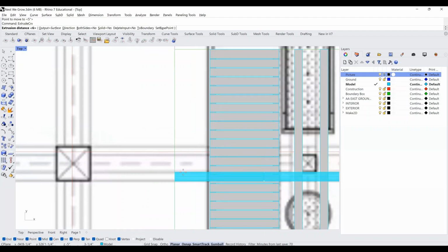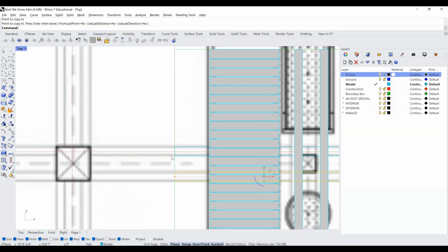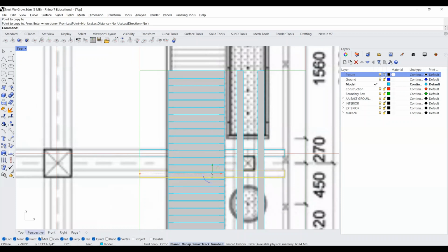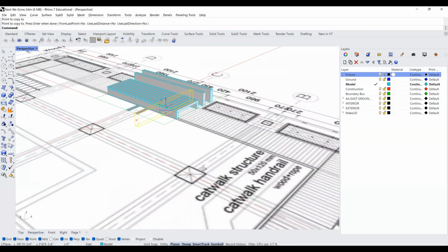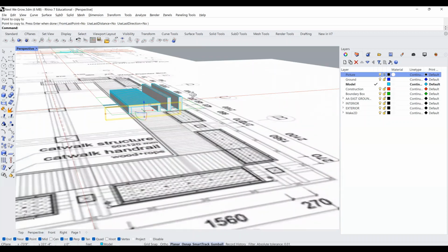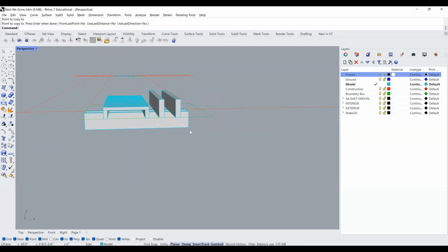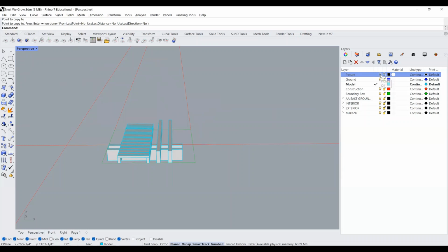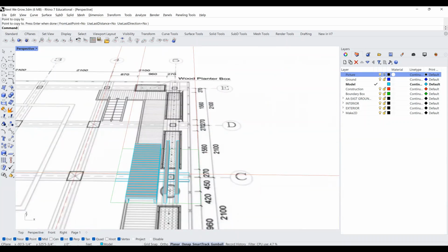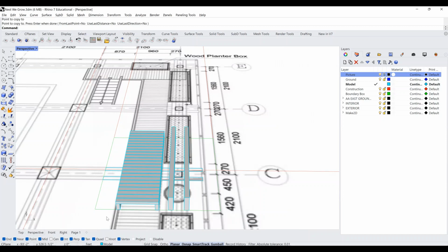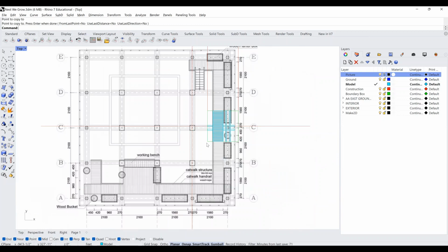So once I've mapped out that outline, I'm also going to copy this again from the top view because I think that's a bit more accurate in this case. And I'm just going to turn off the center snap for now. And now I have my two columns, or two beams, sorry, that rest on top of each other. Or at least the catwalk, the beams that rest on this beam. And so now I'm going to go ahead and make the columns that are cut vertically.